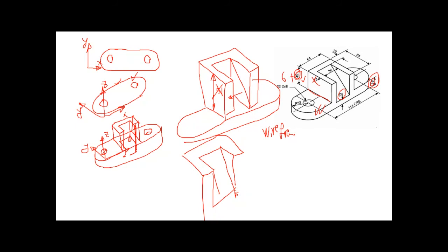Am I clear about this one or not? Okay. Now, you still have that problem. This solid part is there, right? And this one should be 6 below. What can we do here, guys, in this case? Offset for what? Okay. Here is exactly what we need to do, guys. First of all, you go for that one, and you make press pull. You see this triangle all the way down, and you make press pull. Then you will end up with a shape like this.